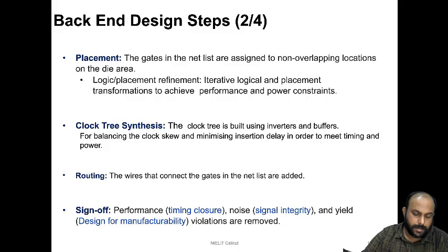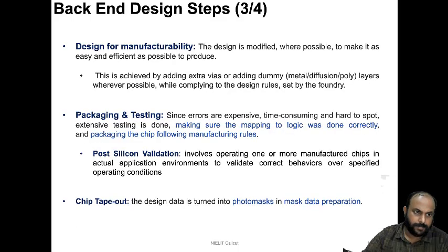In this step called physical verification and sign off, it checks whether the design meets timing performance, that is, there are no setup time violations, no hold time violations, and so on. Similarly, there are no noise issues, it has sufficient signal integrity, and it can give a proper yield. There are no such violations in respect to timing, signal integrity, or DFM. So these things are taken care of in the physical verification and sign off step.